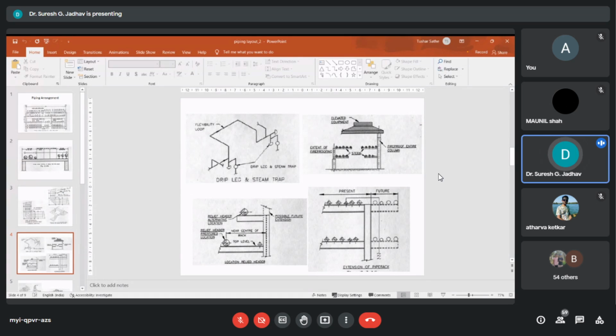So that is a typical arrangement of a hose station along the rack, and the overall pipe rack design must meet the current needs as well as the expansion plans without major modification. Heavy large diameter piping may be laid below the ground on sleepers as established by economics.